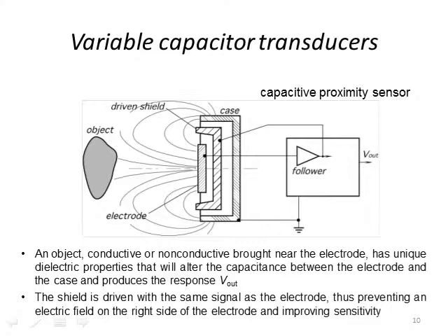Quite a simple concept, but it can be quite effective. And you can basically, by placing this driven shield, this provides a much higher sensitivity compared to not having a driven shield located in the circuit.